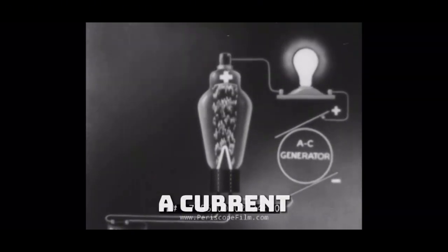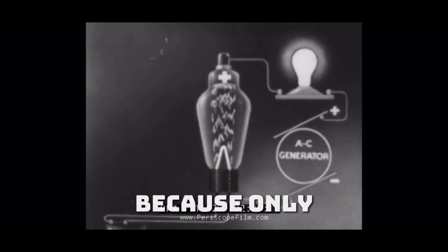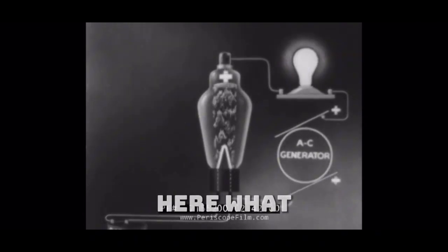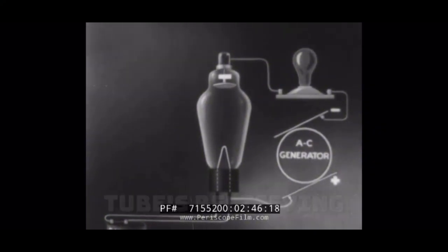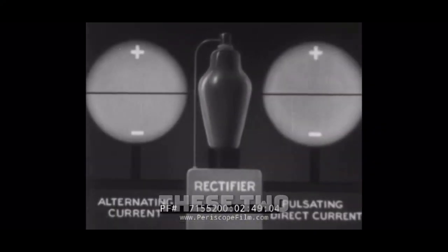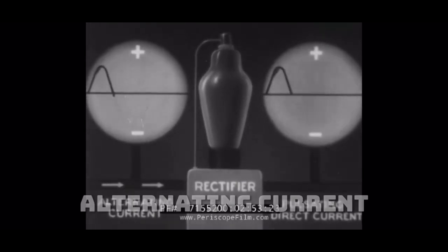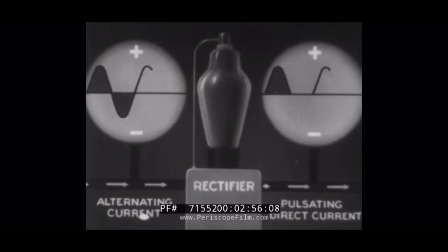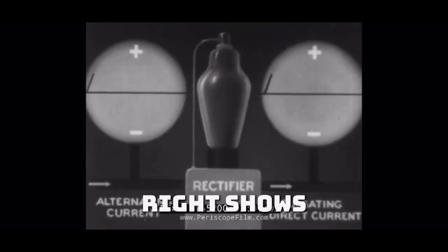As you study this circuit diagram, note that only each positive half wave of AC voltage will now produce a current when the anode current flows. In other words, because only the cathode can emit electrons, we have here what amounts to a one-way street. We can visualize the result of the tube's rectifying action with the aid of these two oscilloscopes. The one on the left shows alternating current coming in. The one on the right shows pulsating direct current going out.